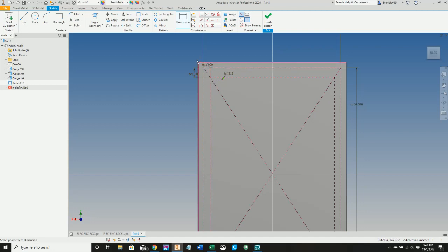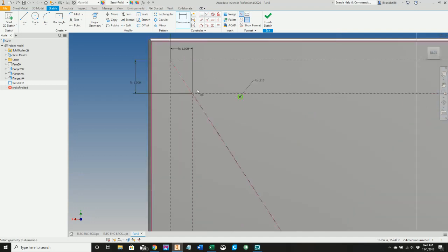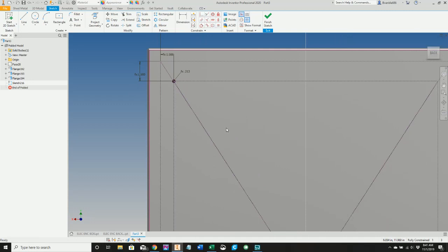These are variables that we set up in the parameters, and now we can take our circle, grab a hold of the center of it, and slide it over to the very end point, and you'll see that little green dot in the center saying that it's fully constrained, and then it turns black. So I'm going to hit Shift Control C and place more circles, or you can come up here to the little circle function and click on the icon, but I use Control Shift C again because I'm a keyboard junkie, and you can see that I've got the construction function still initiated.